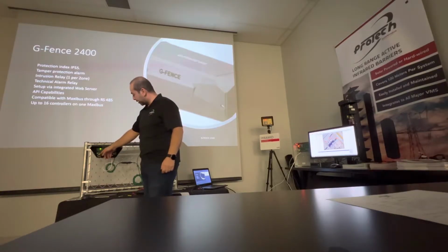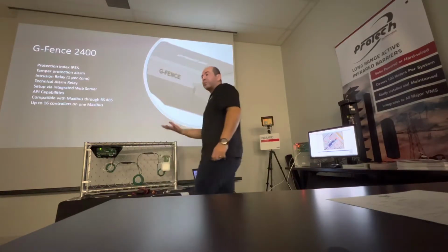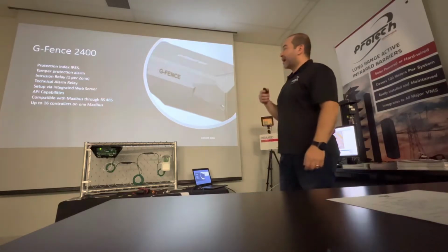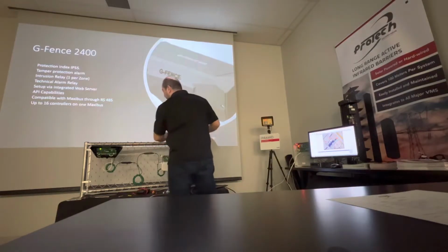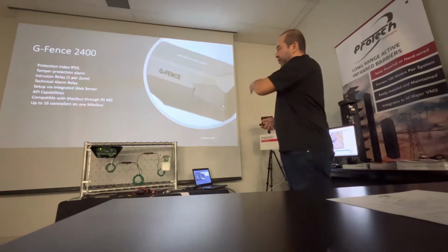And then you can create virtual zones. Each virtual zone will physically activate one relay. So relay number one will be dedicated to zone number one and so on, up to 10 zones. And the virtual zones, you can set whatever you want: sensors 1 to 8 in zone number 1, 9 to 12 in zone number 2, and keep going until you reach the end of line.